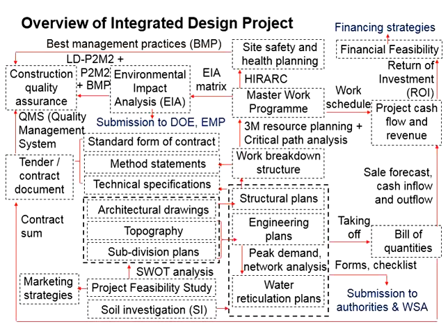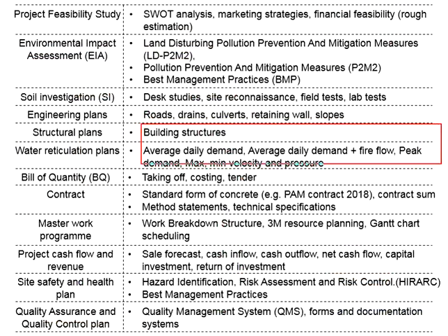This requirement shall be on the basis of the water supply agencies that the development project is subject to. Therefore, you will need to perform the network analysis to calculate the pressure under various circumstances, such as under the average daily demand, under the average daily demand plus the fire flow, and also under the peak demand, as indicated here.